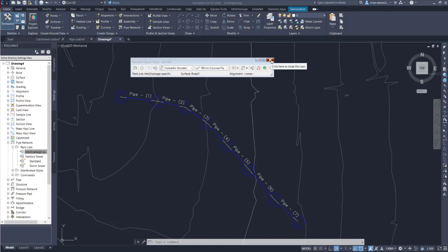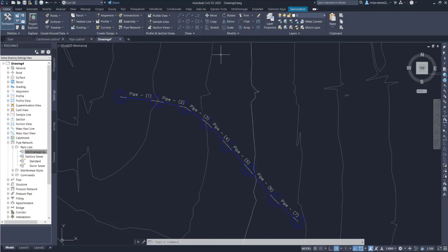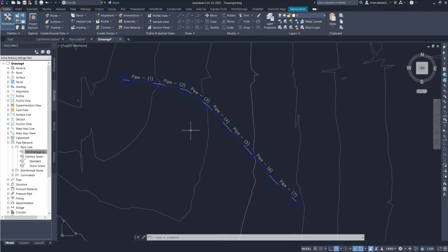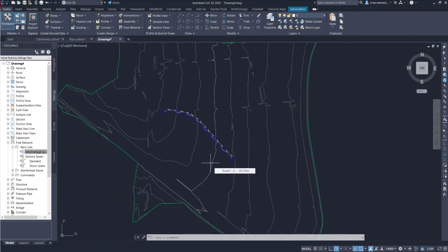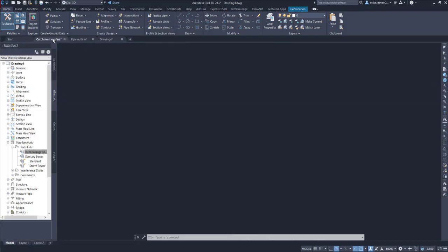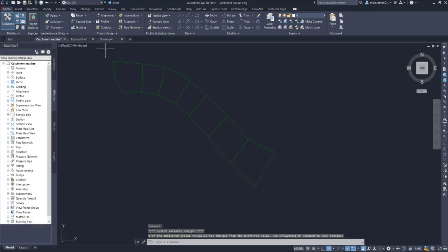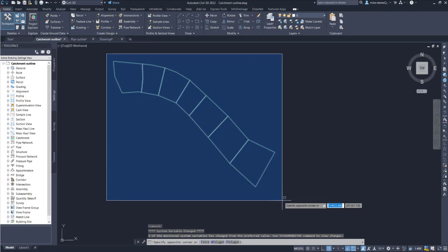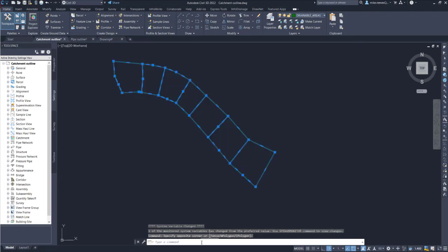Next thing I'm going to do is to create my subcatchments. So one of the first things I've got to do, similarly, I wanted to make sure I have my subcatchments in the right place. I could just digitize them here straight within Civil 3D. I thought I'd take some boundaries that had already been created and copy them in and then snap to those. So I'm going to copy them, and a similar process, copy these to a clipboard,